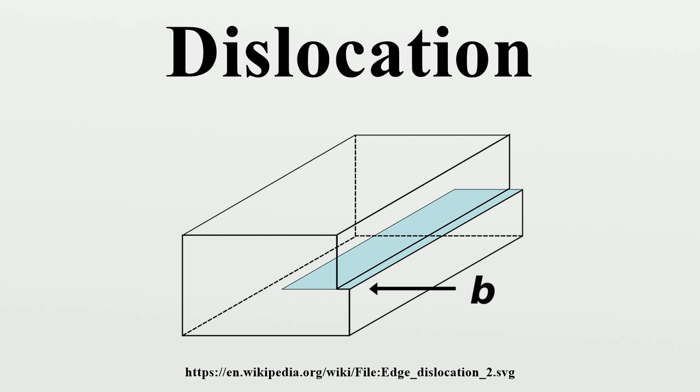Transmission electron microscopy can be used to observe dislocations within the microstructure of the material. Thin foils of metallic samples are prepared to render them transparent to the electron beam of the microscope. The electron beam suffers diffraction by the regular crystal lattice planes of the metal atoms, and the differing relative angles between the beam and the lattice planes of each grain in the metal's microstructure result in image contrast.